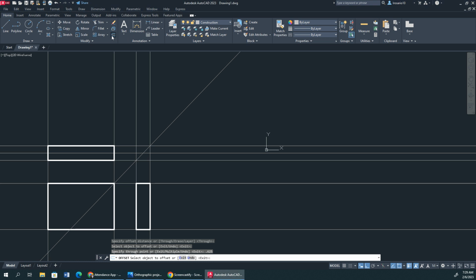What I'm going to do here is offset this line by 3. That's supposed to be our center line of our circles. As you see here, it's shared within relations of the front view. Now, I'm going to offset this once to the left, 0.5625, once to the right, 0.5625, and this is supposed to be where our circle is going to be, as you can see right here as well. Okay?